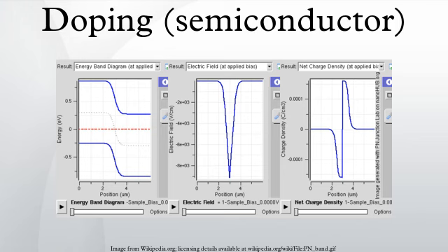These are related to the value of the intrinsic concentration via an expression which is independent of the doping level, since EC minus EV does not change with doping. The concentration factors NC(T) and NV(T) are given by an expression where me and mh are the density of states effective masses of electrons and holes, respectively, quantities that are roughly constant over temperature.